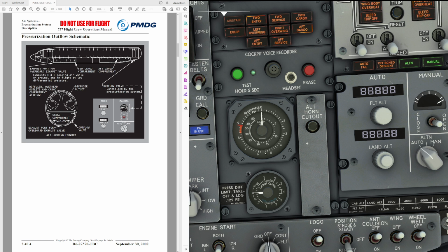Now, be aware of one big threat over here. During normal operation, passing 10,000 feet, the big needle is at the 4 position, and the small needle is still approximately close to the 0 position, because the cabin altitude has not significantly increased in this time. However, if you are flying unpressurized and you're passing 10,000 feet, the small needle will be around the 10 position, so quite close to the 4, while the big needle is going to indicate 0 because the inside pressure equals the outside pressure. So a reversal of those two needles, for the case that you have forgotten to set up the pressurization system correctly, is looking very similar to one another.